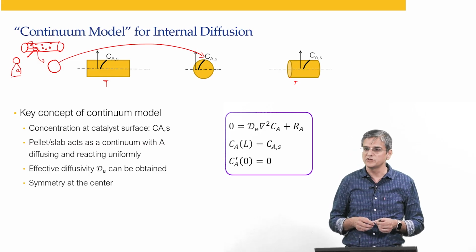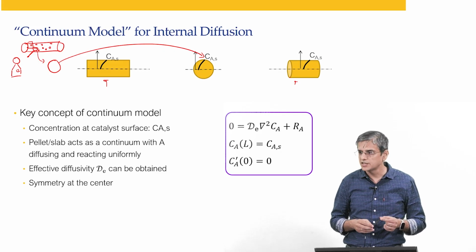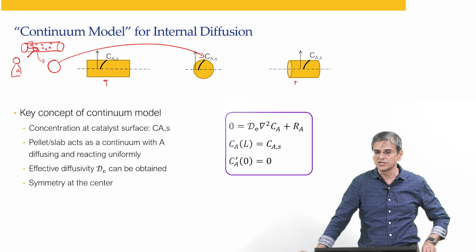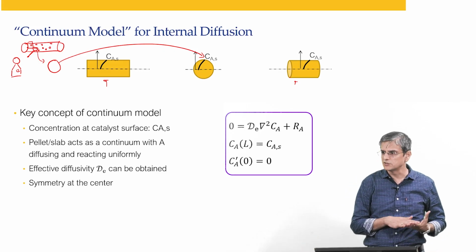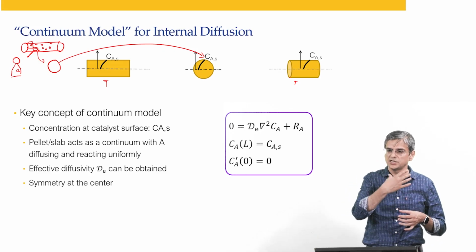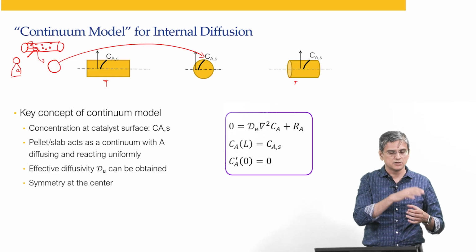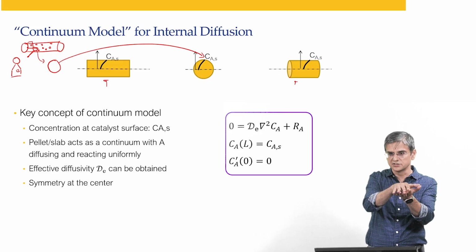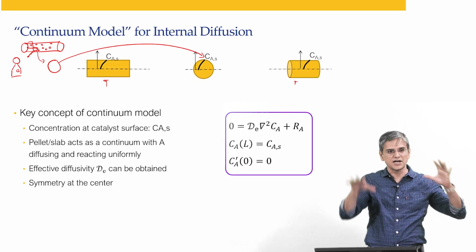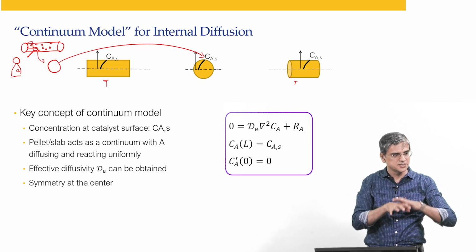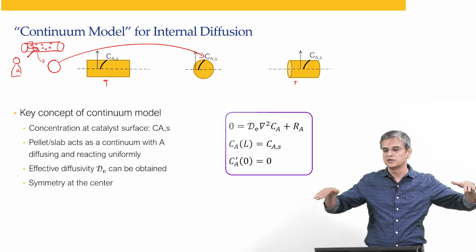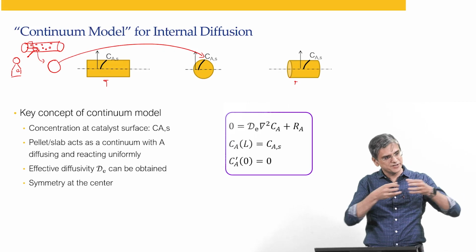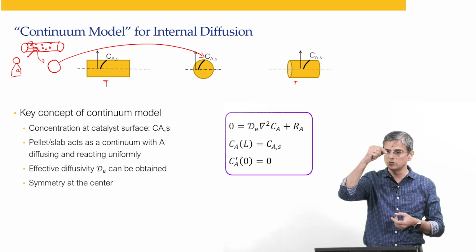It is because some of the materials, so one of the materials that I worked on when I was in the industry, was anisotropic, I think I talked about that once. Take the MOF material and add some graphite to it and then compress it, and the compression is in this direction. So the graphite is not randomly arranged, but gets arranged more or less in the xy plane and hardly anything in the z plane. So the thermal conductivity is very high in this plane, but very low in this plane.